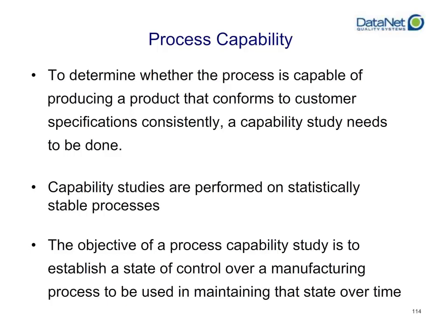If your process is currently out of control because your most recent subgroup is out of control, or you have a lot of out of control conditions within your data set right now, you cannot do a capability study. It is a meaningless capability study because your process is in a state where it is highly likely that it is currently shifting. Therefore, you don't know if it is capable at that point.